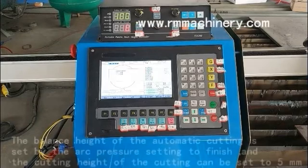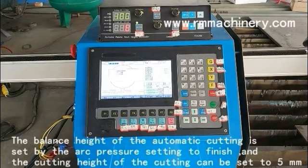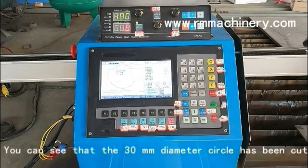The balance height of the automatic cutting is set by the arc voltage setting, and the cutting height can be set to 5 mm. You can see that the 30 mm diameter circle has been cut.